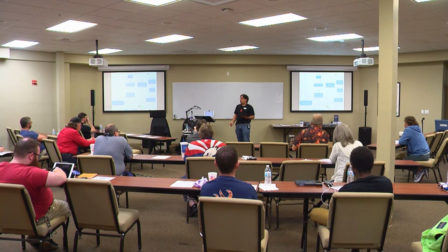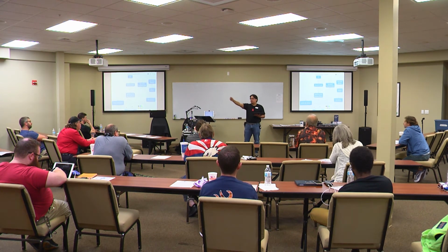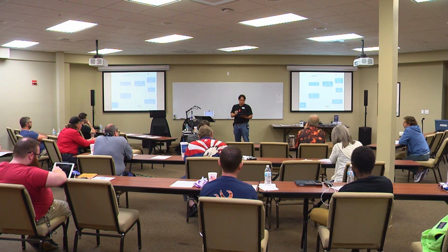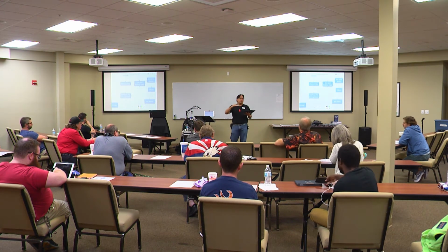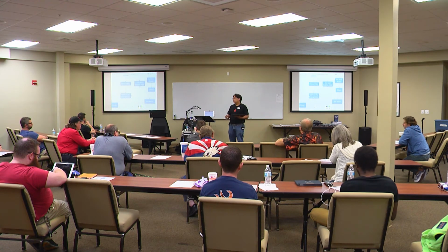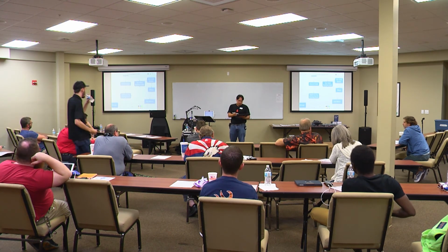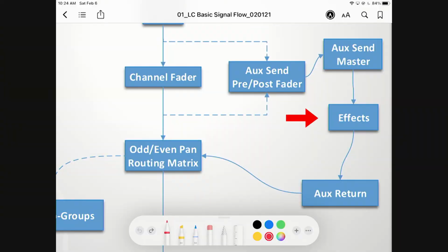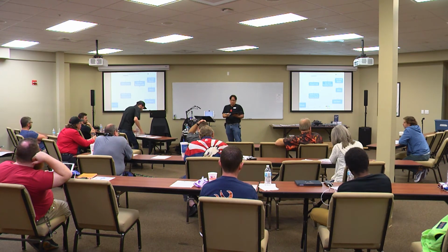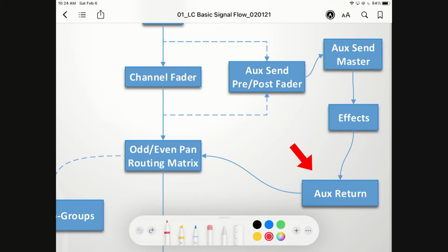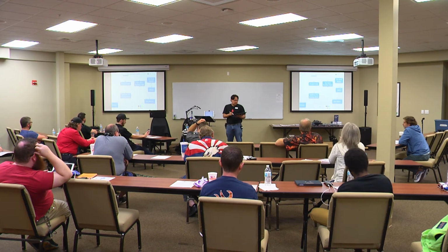So if you're looking at your console, you're going to go, oh, I want to send this to aux 1. Turn it up. From there, it's going to go to an aux send master. So you're going to find that aux send master. That aux send master typically goes to an effect, but it can go to monitors. It can go to whatever you want. Sky's the limit. Knock yourself out. And then from there, it can go to effects or not, or to wherever. If it's going to effects, typically the effects will go to an auxiliary return, which is actually what aux stands for. Auxiliary return, and that'll come back in.